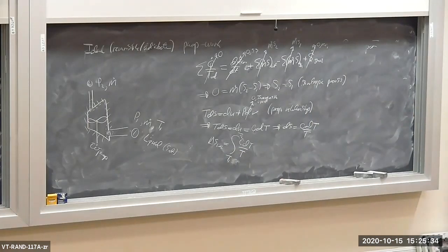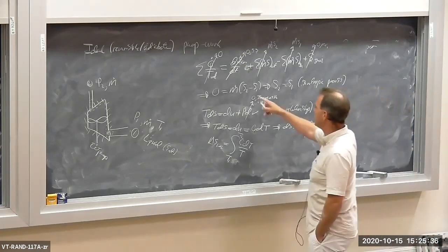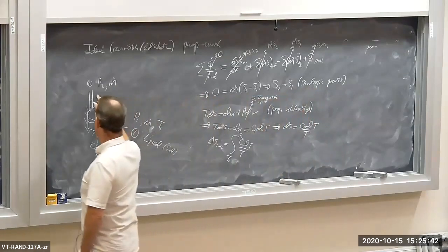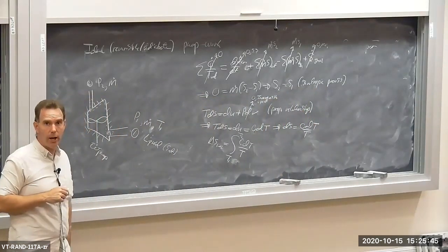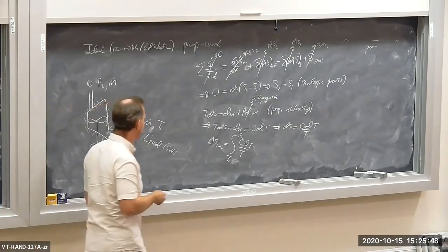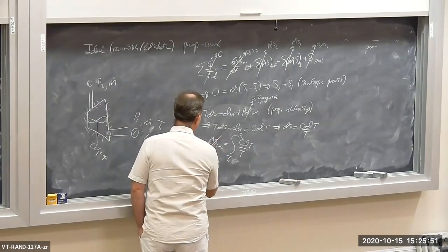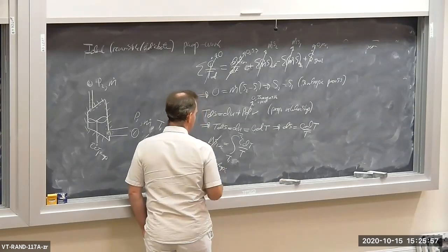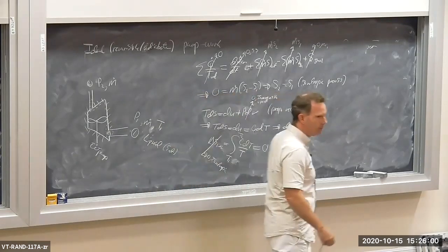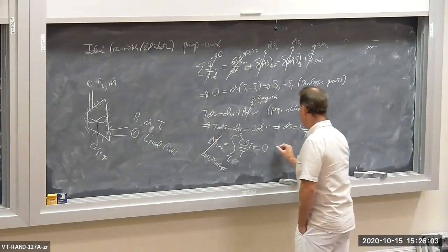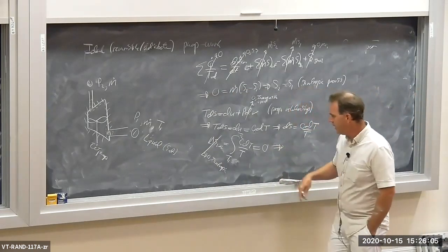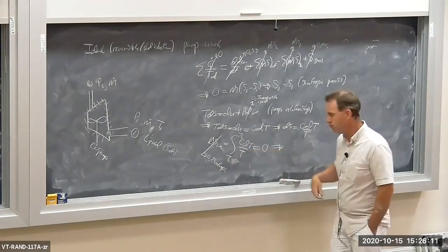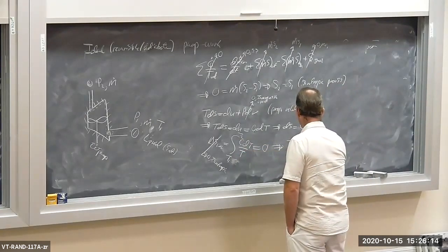Now, what is delta S for this process through the pump? It's reversible adiabatic, therefore delta S is 0. It's an isentropic process. So delta S is 0 because it's isentropic. So this thing is 0. Therefore, getting a little cluttered here, but try to follow along. If this integral is 0, it means that this temperature change is 0. That means T2 is equal to T1.